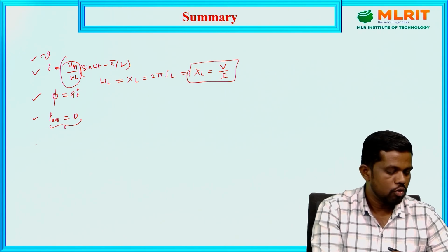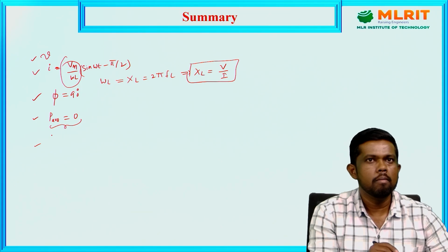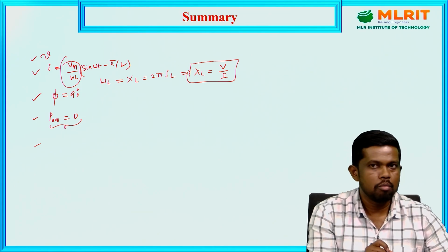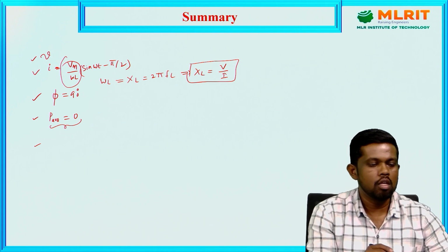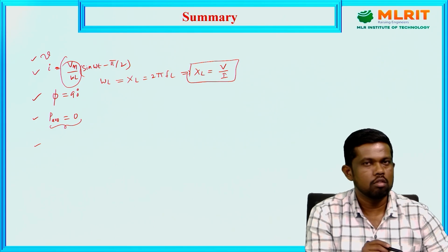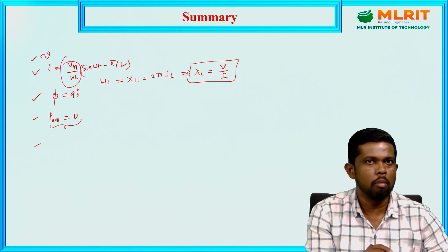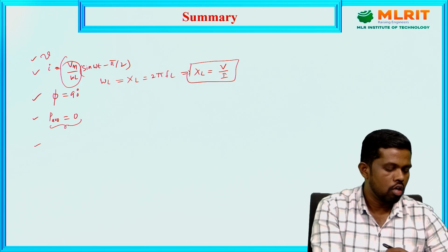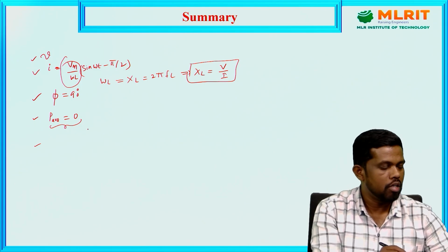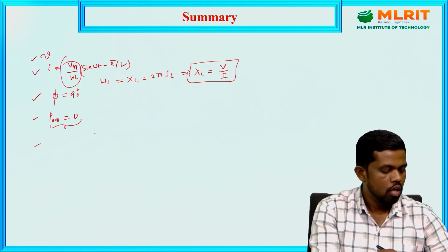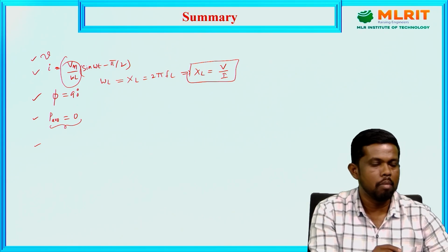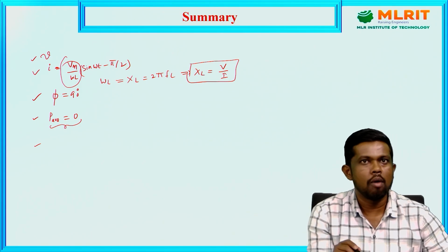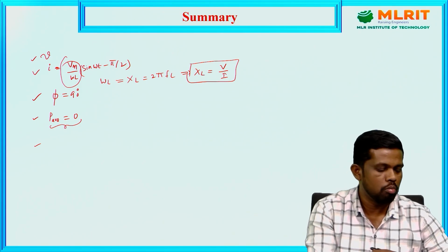After that, we also drew the phasor representation of the voltage and current. It clearly shows that the current of the circuit always lags behind the voltage by an angle of 90 degrees. Based on this, the power cycles over the 2 pi span occur twice, because we got the instantaneous power in terms of sine of 2 omega t. So we got 2 power cycles in one complete cycle of the applied voltage. The instantaneous power taken by the inductor is Vm Im by 2 sine of 2 omega t, so the average power consumed by the inductor over a complete cycle becomes 0.